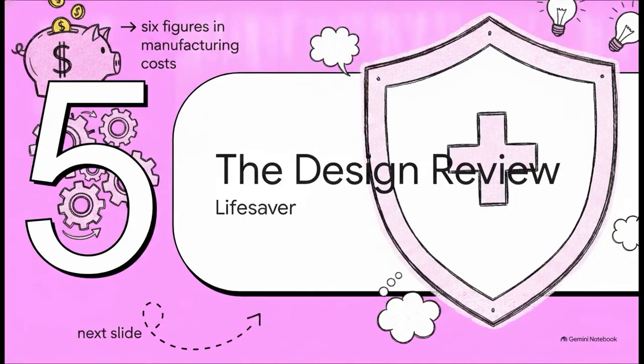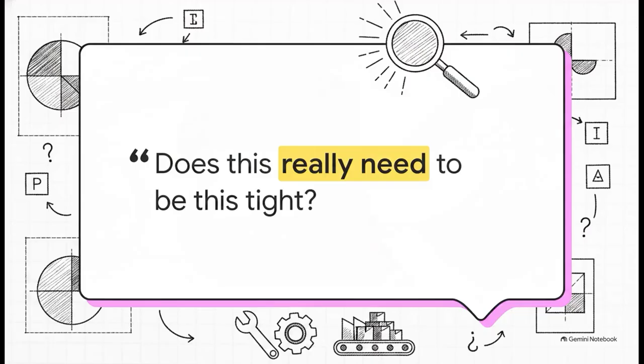Okay, Section 5, the Design Review Lifesaver. We are entering the phase of this explainer that has literally saved real production programs 6 figures in manufacturing costs. If you take one single practical habit away from this session, please let it be this next question. You must rigorously ask this single design review question of every single blueprint, of every single feature control frame. Does this actually need to be this tight? Seriously. Do not accept "we always do it this way" or "it's just a standard block tolerance." Force your team to justify the tolerance against the functional requirement and the shop floor's actual process capability.